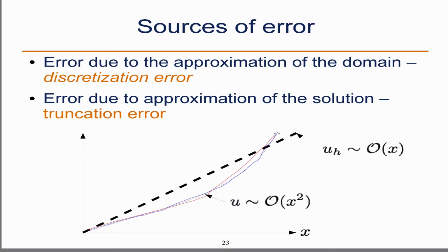So in this case, if instead of using a linear interpolant, I use a quadratic interpolant, with 1 element I can match the solution exactly.